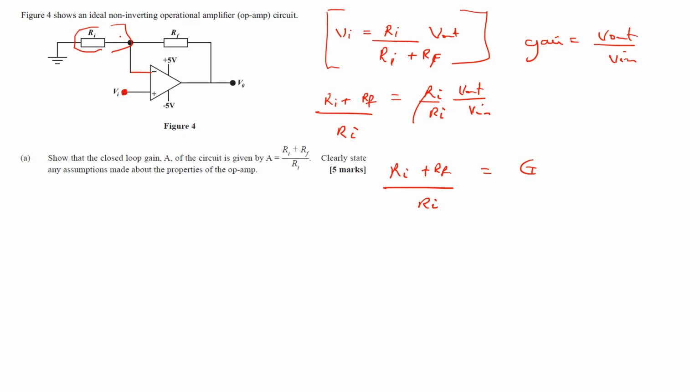So how do you know it's a non-inverting operational amplifier? That is when the V in is connected to the non-inverting terminal. The non-inverting terminal is the positive terminal. The negative terminal is called the inverting terminal. So, ladies and gentlemen, what we expect here is that if the voltage at the non-inverting terminal is positive, we mean that it starts out positive.